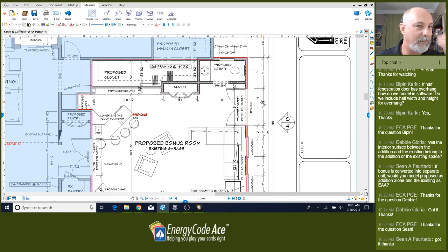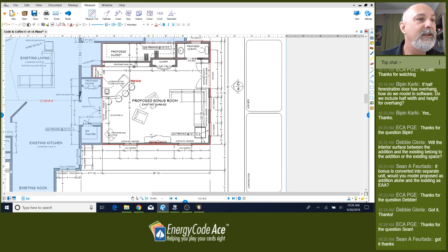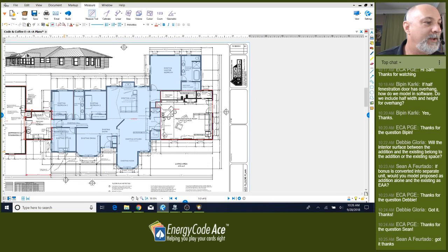If you've taken my CA exam prep workshop, the res workshop, we talk about strategies for window dimensions if you're going to be doing overhangs, inputting that so you can avoid the multiplication factor on your fenestration sheet. So if you ever run across that, you know what I'm talking about. I may do a YouTube episode on that in the future. So 2 windows, 3050s, those are 15 square feet apiece. Good. I think we have our takeoff done. I didn't see any skylights. If you saw skylights here, no, I don't see anything.